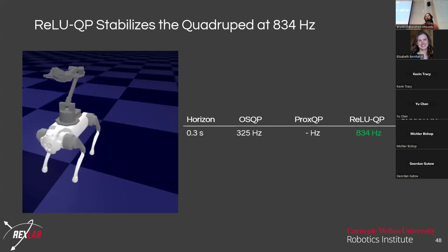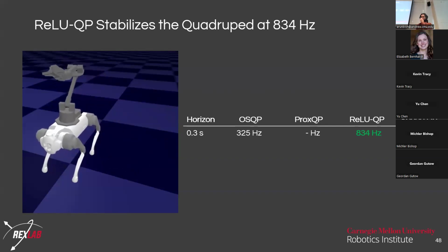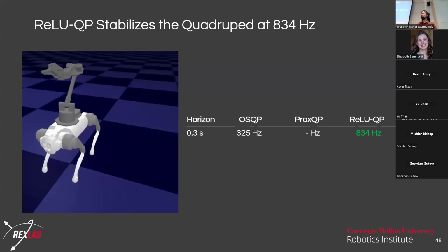And then in addition, you notice the speed here is definitely a great gain because we're getting close to the limits on actual hardware of how quickly you can send torque controls over the communications they give us. But it's not 20x like Atlas. And we think one reason for that is, one, we have the force constraints that we're not doing this feedback trick on, so there's some sparsity in the problem.